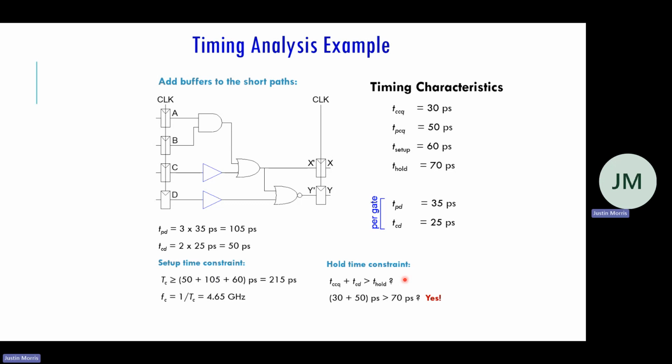And your quiz will look something like this. You'll be given some registers, some combinational logic in between registers. And I want you to tell me if there's a setup time violation, hold time violation, or I can ask you what is the minimum clock period of the circuits, things like that. And we will do some practice next week.